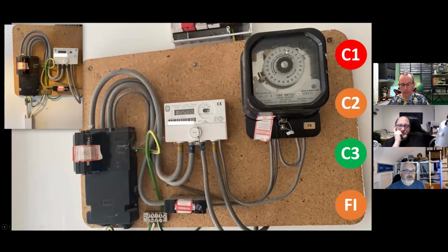So for everyone watching, that on the right is a good old-fashioned time switch. Basically, you take a supply out of the DNO head, take it into a little fuse, it then feeds into the time clock, then loops across and back into the meter, and that just sends a little signal to say change from single to second rate. Basically, your Economy 7 or whatever. Then your earthing terminal is obviously a connection into the side, which is a connection into the neutral.